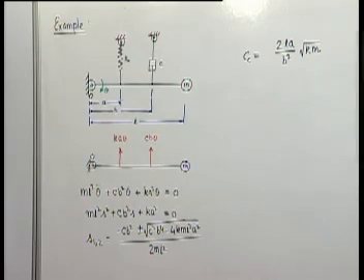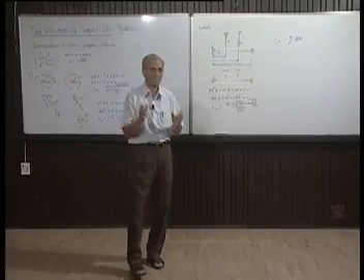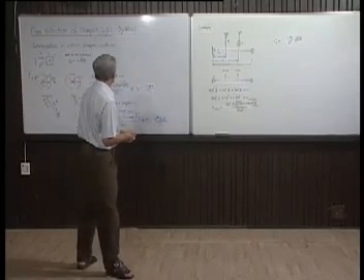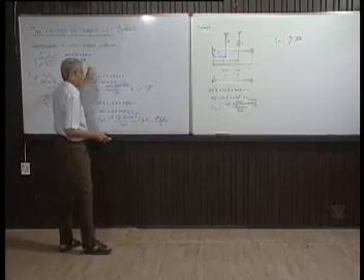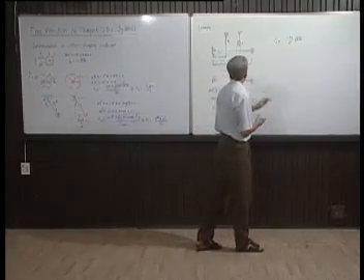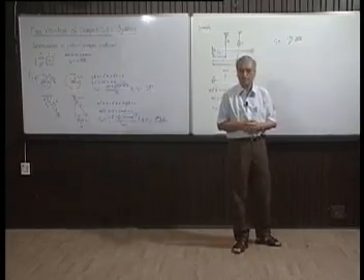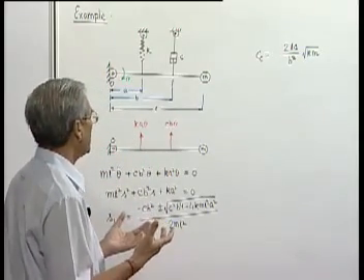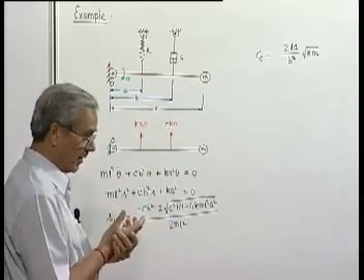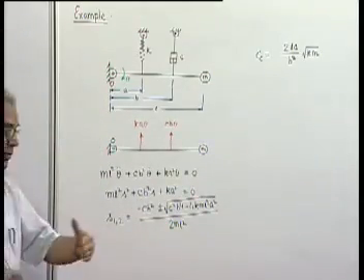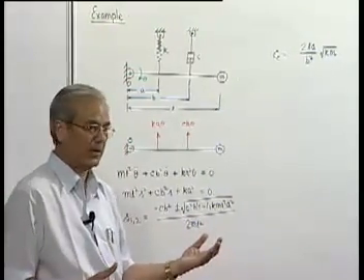So therefore, we have to keep this in mind that for each and every individual configuration or system, there exists a different expression for the damping coefficient. So, you should never consider that the critical value of the damping coefficient is always given by this. Each time it has to be found out. So far as the application of the critical damping coefficient, I think you understand that the practical applications will be in all such cases where you don't want the system to cross the equilibrium position, or rather approach the equilibrium position with negligible velocity.